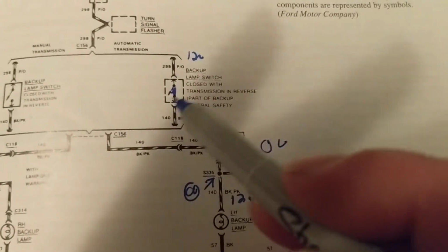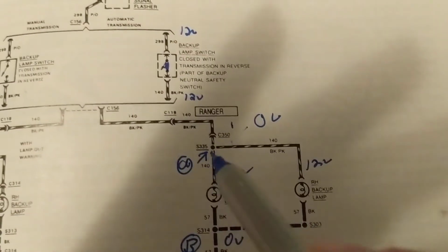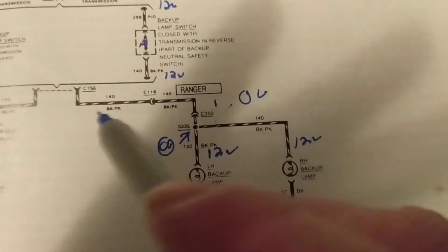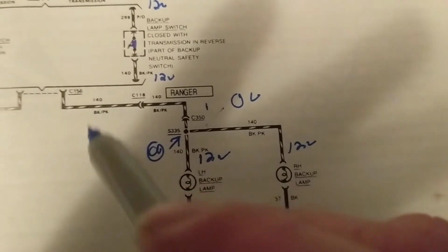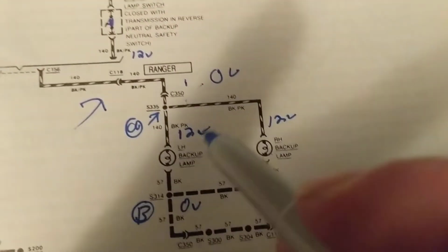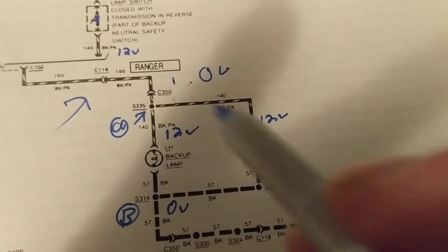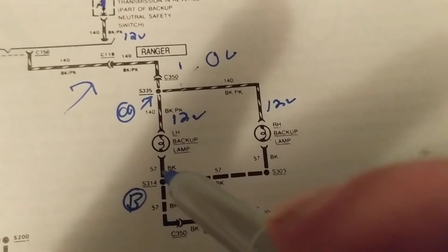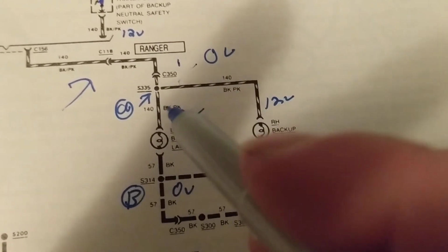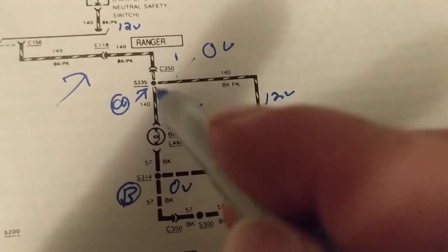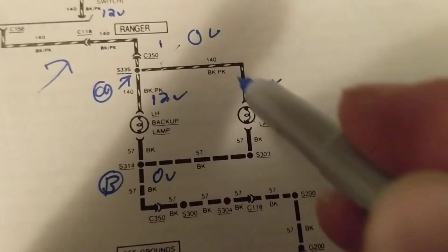Of course, I'll say the switch must be in the open position, or what else? This wire must be broken. Why do I pick on this wire? Why didn't I stress this wire? Well, if this wire is broken, I can still have current illuminating the other one. And if this wire is broken, I can still have current illuminating this one.